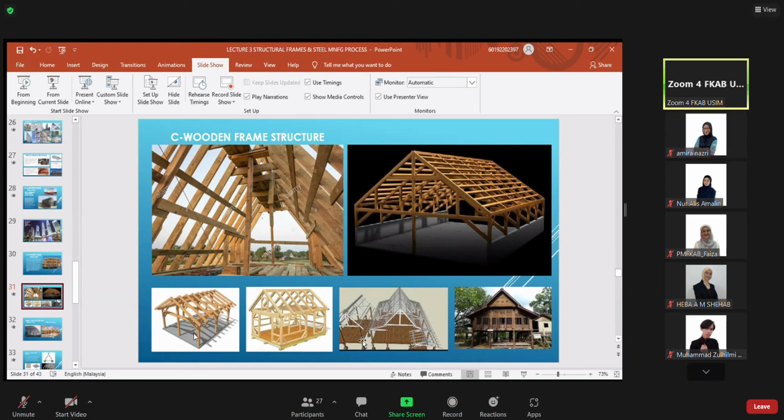It is similar to our Malay kampung, the traditional Malay kampung. It's all frame structure. Start with columns, then you have joists, bearers, joists, rafters, all the frame. The rest are infill panel. This is the finished product. The walls and windows are infill, between columns, supported by the bearer, which supports the joist and then the floorboard. This is for ventilation purposes, because of the hot air in Malaysia, the hot air will be flushed out through this gable end. So this is timber.